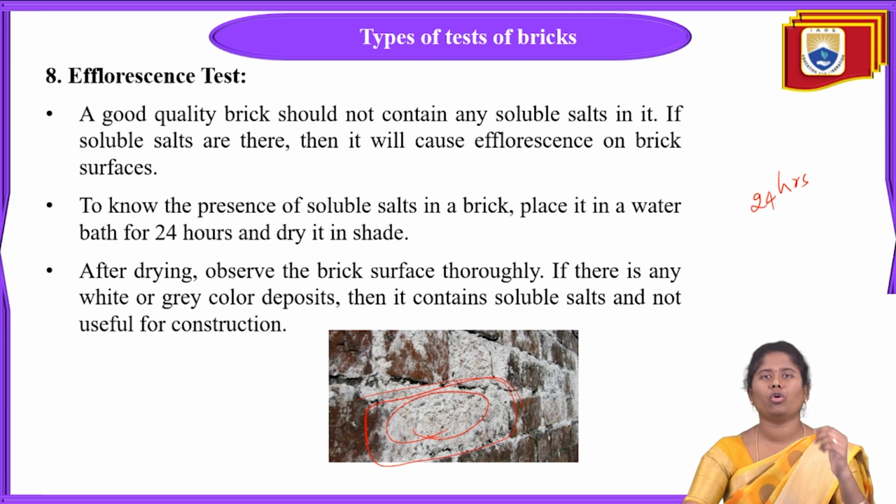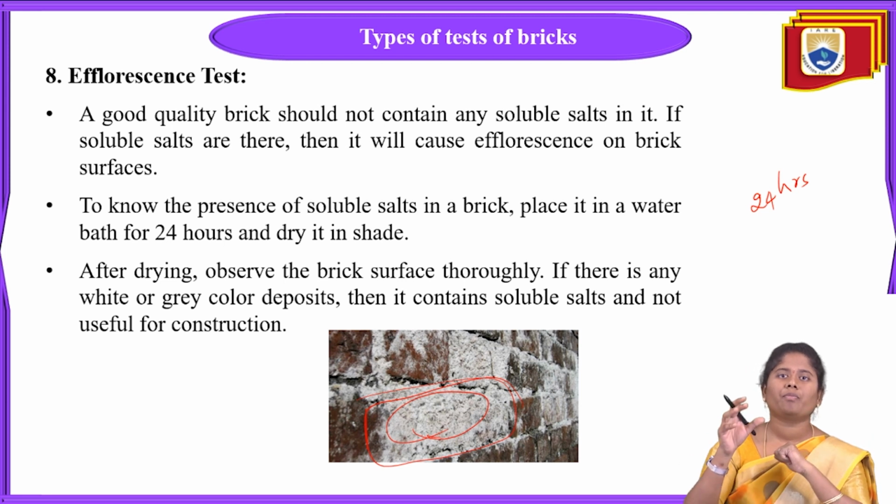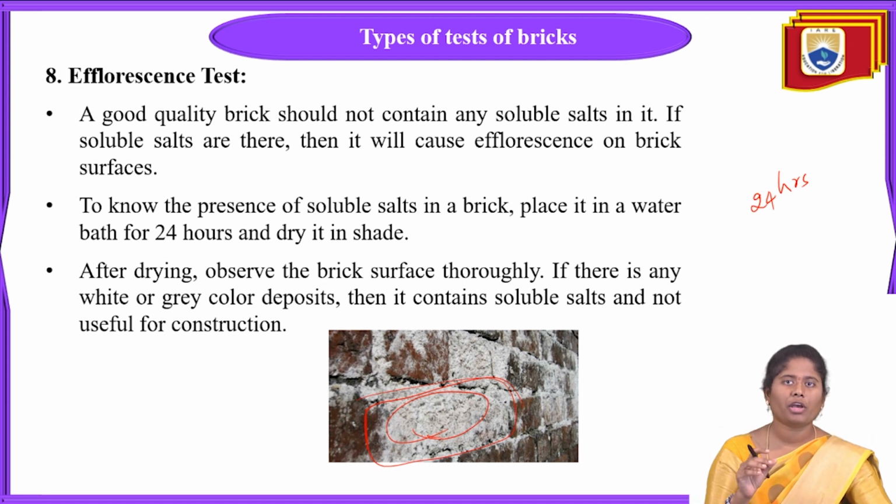Why we are doing this test is to know if our brick has any soluble salts. For that, we are going to take one brick and keep that brick in the water bath for 24 hours. After 24 hours, take out that brick and dry it in the sun radiations.